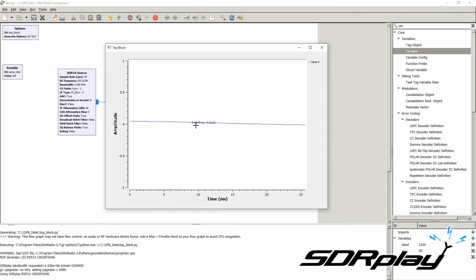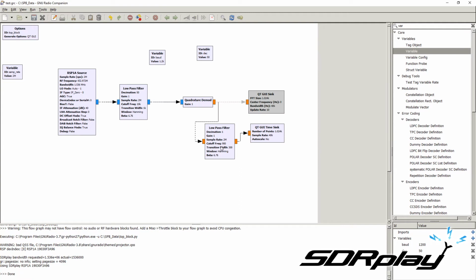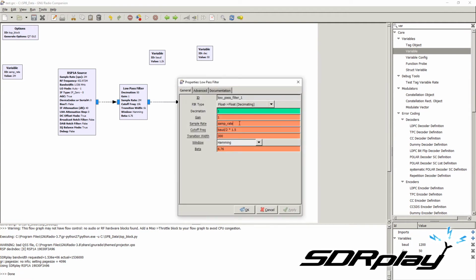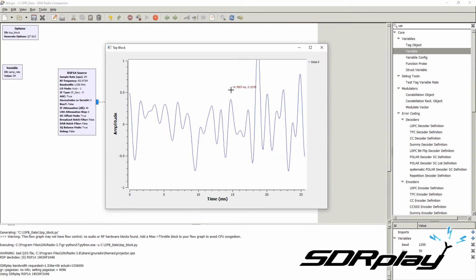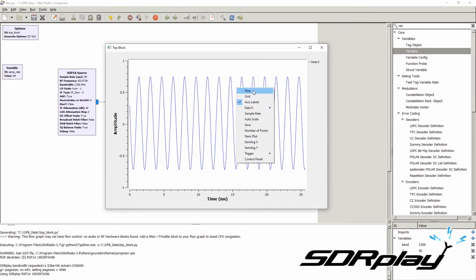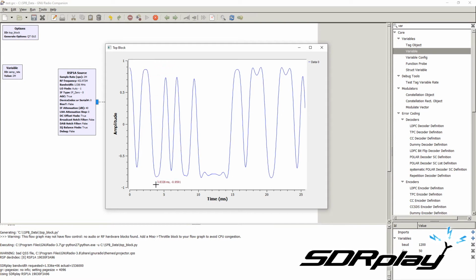And there is some problem with the signal. We actually set the wrong sampling rate, because the default is 2 MHz, but the sampling rate is actually divided by the decimation. So let's divide by DEC, and let's try again. Perfect. Now let's stop on our signal, and you can see now that the high and low transitions are very smooth and very clear. There is no more ringing. There are no more big oscillations on the values. Okay, it looks a lot better.